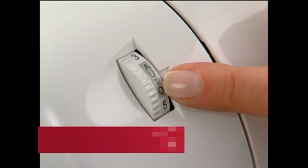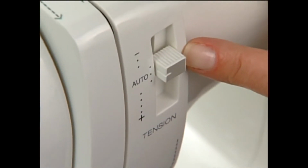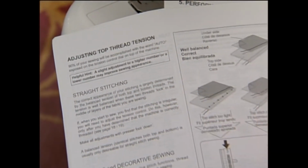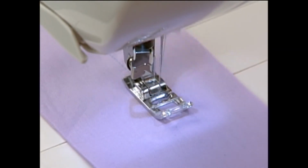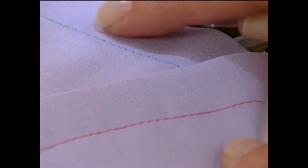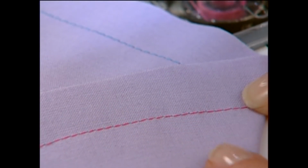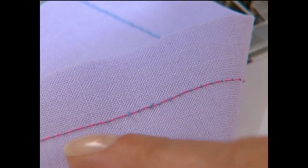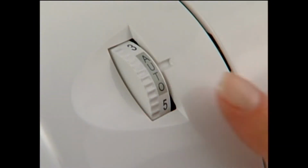90% of your sewing will be done with your tension control set in the normal or automatic range as indicated by the instruction manual for your model of machine. The correct appearance of your stitching is mostly determined by the balanced tension of both top and bobbin threads. For straight stitch sewing, the tension is well balanced when these two threads lock in the middle of the fabric layers you are sewing. If, when you start to sew, you find that the stitching is irregular, you will need to adjust the tension control.